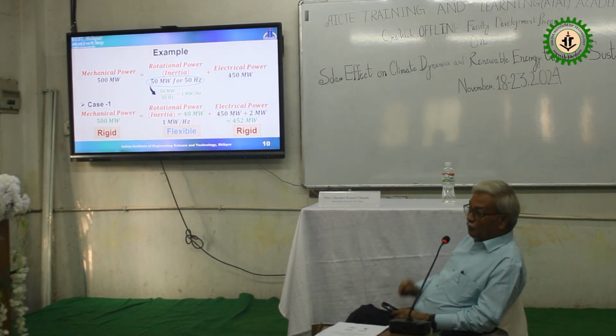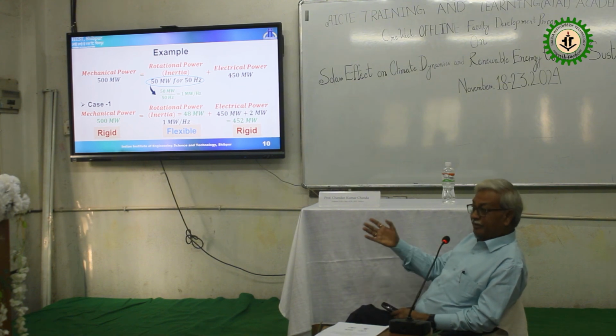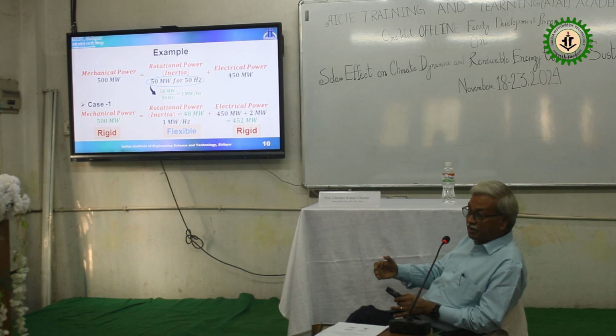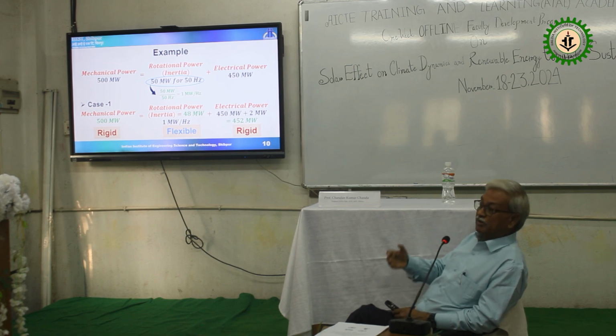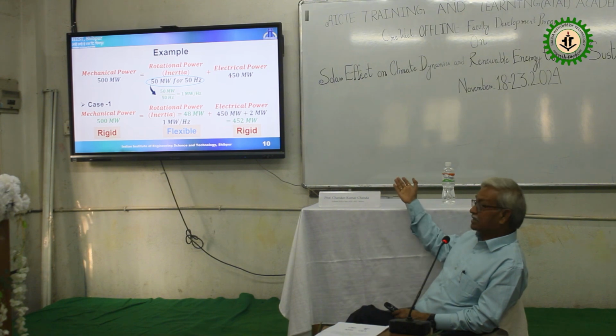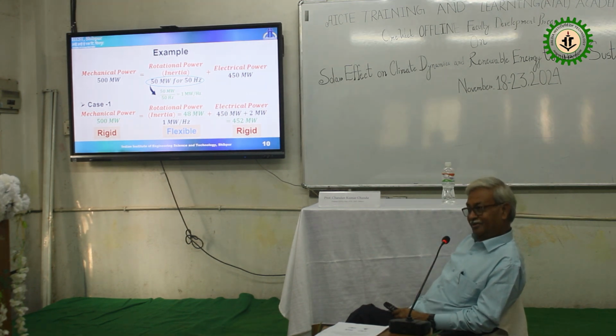The question is, we have to operate the generator or the grid within a frequency band. If you talk about the synchronous generator, we cannot go below 49.5 or above 50.5. There is a frequency band. There is an under frequency and over frequency relay. It will trip the system, and we don't require the system to trip. If suddenly the demand comes and the frequency relay trips, all generators will trip and the whole grid will black out. It's not possible. We need power, we will deliver the power.